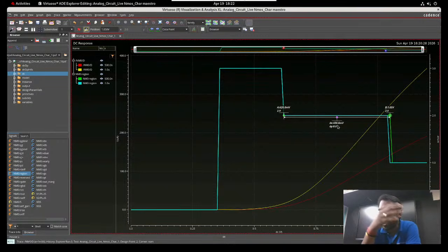But basically, if you know the ID versus VGS graph, if you know the region of operation, if you are good in understanding of node voltage and what is the gate voltage, what is happening on the gate side, that will help you. If you go for a basic current mirror or common source amplifier or differential amplifier, everywhere I am using this only.